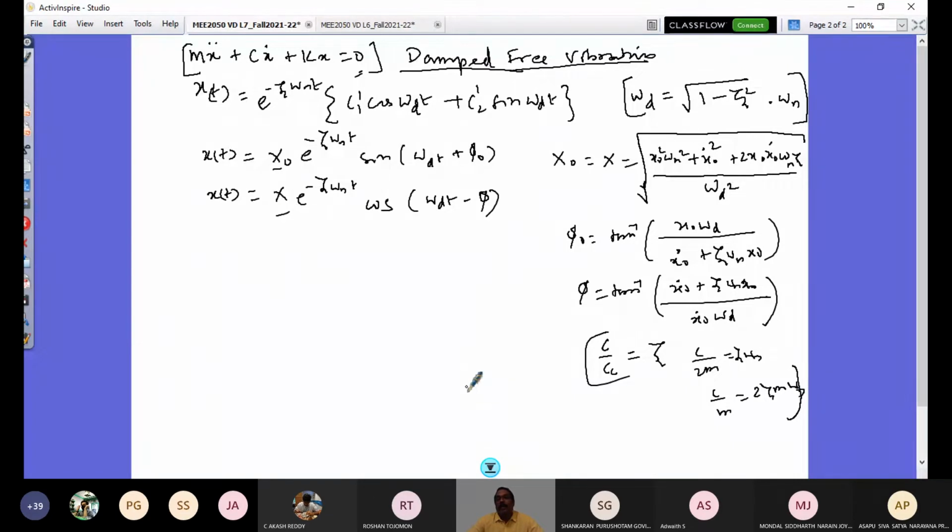that's called a critically damped system. So that will not vibrate. There is no oscillation. That's called aperiodic motion. If zeta value is greater than 1, then it is called the overdamped system. That is also aperiodic in nature. The least damping required for aperiodic motion is the critically damped system. When it is more, then it is an overdamped system. The shortest time that it takes to come back to the mean position is given by the critically damped system. We will see that in a while.